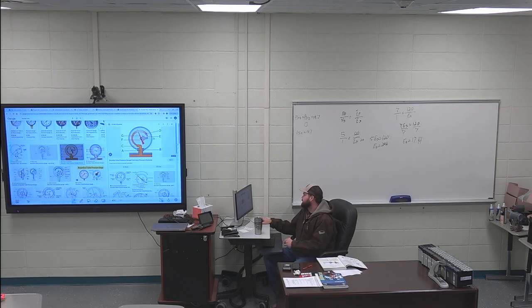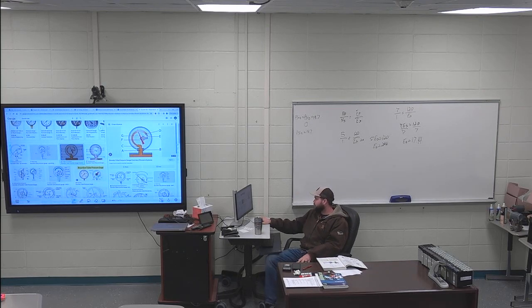So just looking at this picture that's on the board, have I talked about these at all? No, I haven't. I've taken the instrumentation classes, mixing in with what I've told y'all. So this would be a gauge like you would measure your tire pressure with, right? So pressure comes in the bottom here. This is a hollow metal tube. So as pressure is pushing here, like my hand is like the C of that Bourdon tube.